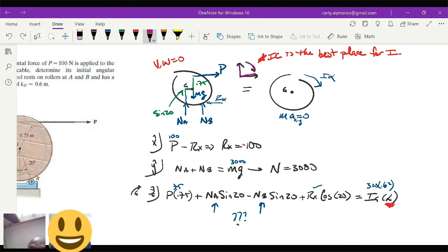How would I want to write that? I'll do something like this. And so they net out to 0. If they're equal to each other, then they'll net out to 0. They'll produce perfectly opposite moments, which means we get the moment produced by the P. The moment produced by the P combined with the moment produced by the Rx has to give me my resultant moment. And that just means that we only have these X forces to create this moment, which looks about right. So I'm going to go with that assumption.